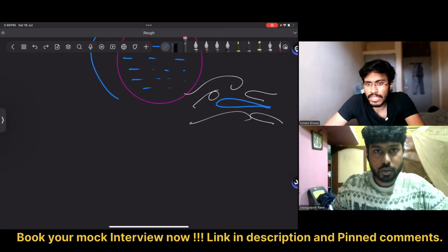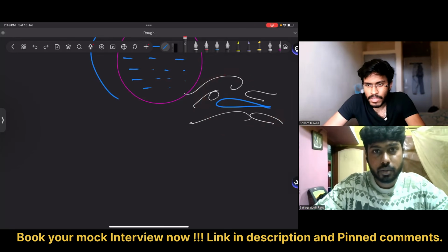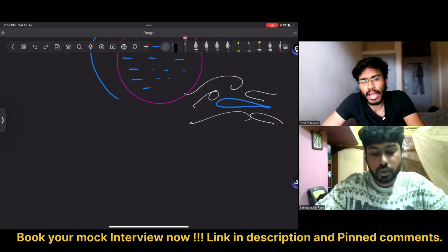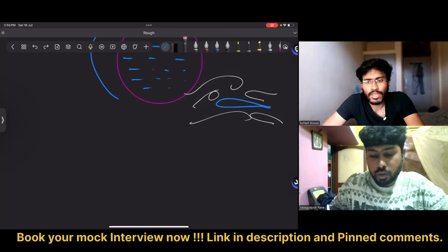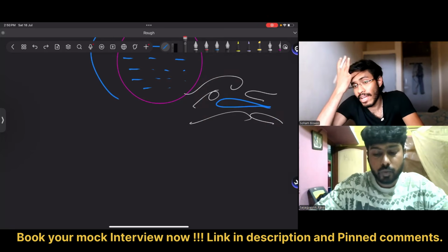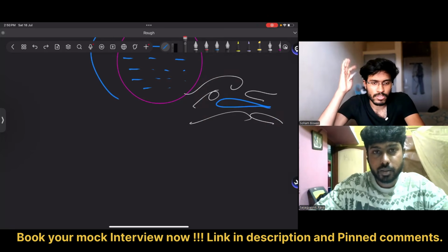So potential flow equations are valid up to maybe transonic flow, not supersonic flow, because there shocks exist. Subsonic and transonic are the ranges where you can apply potential flow. These are simplifications of the full Navier-Stokes equation. Everywhere you can apply the Navier-Stokes equation.